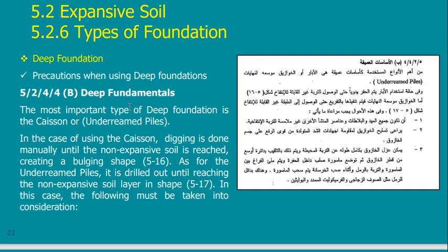And if I use deep foundations, then I should not depend on it in resisting the expansion. I should do my best so that maybe the piles would have double casing around them, so that if the pile wants to move up, it can move freely without affecting the soil around it. It's a problem, so it is better not to deal with it. I've used this type of piles before, but it was a problem, and the benefit of using it was not that good.